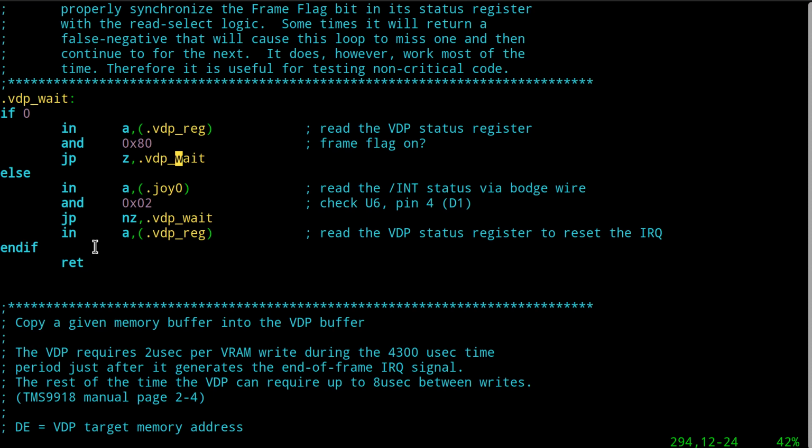The point is, what if I'm late before I get to the wait routine, or I have interrupts disabled for a little while, and then I re-enable them, at which point the interrupt is asserted, which would have the same effect of me calling my wait polling loop a little bit late. Same situation, right? Well, what if I'm late enough that I miss an entire video frame, which can happen, by the way. It seems like an eternity to waste a whole 60th of a second. In this case, it would be a field, right?